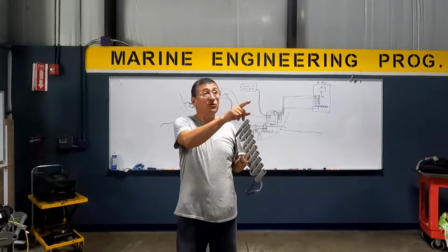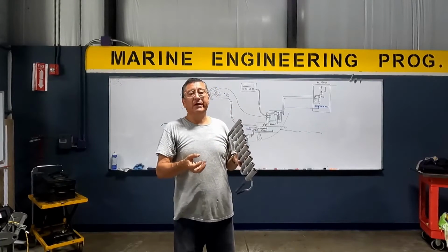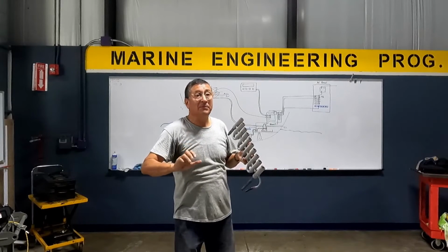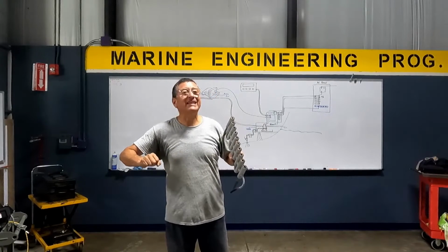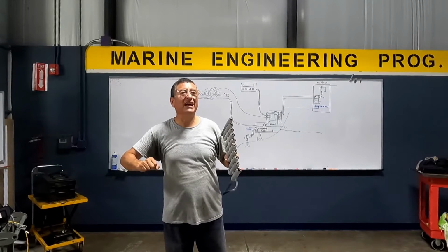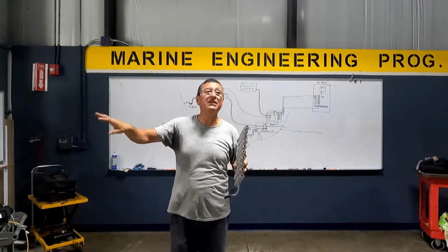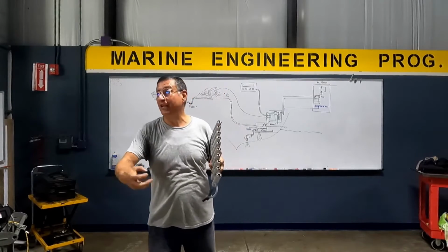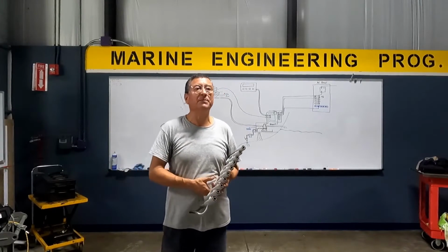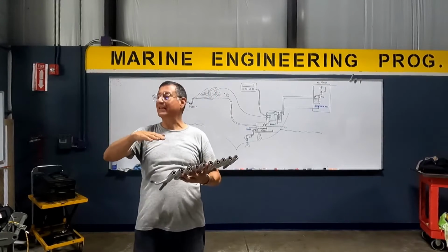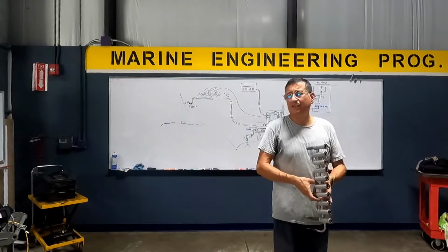If you try to connect the fitting after you stop the air conditioning unit, the pressure in the refrigerant internally is ultra high, no? And it's not possible that the air penetrates. But if the unit was abandoned for 6 months and you try to connect the fittings, you introduce air, 100% sure, because the pressure goes down, no? And the pressure is stabilized. Everybody follow me? Pay attention.